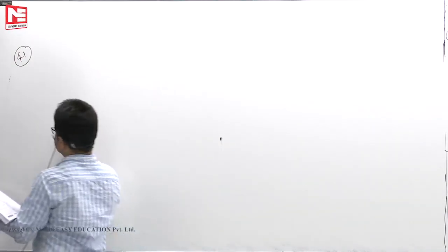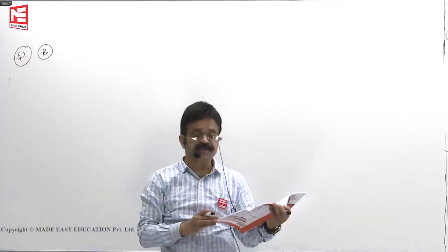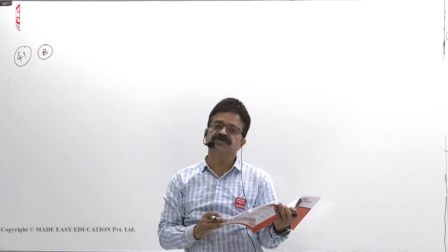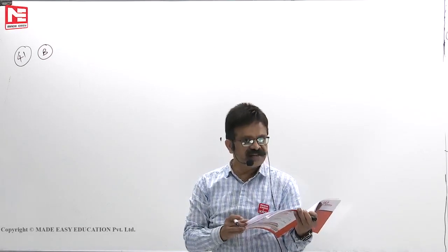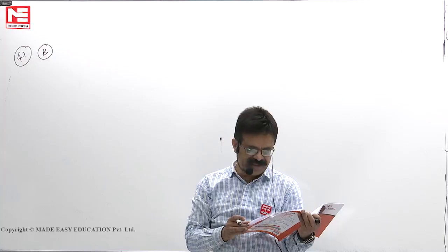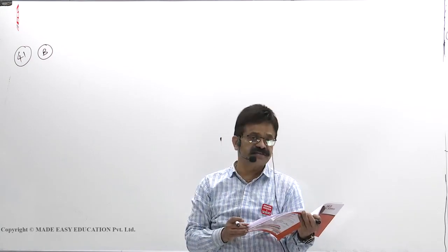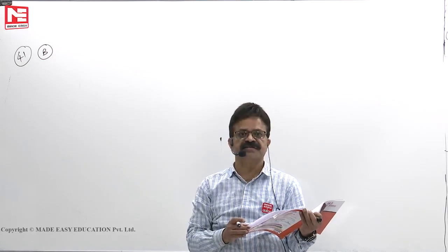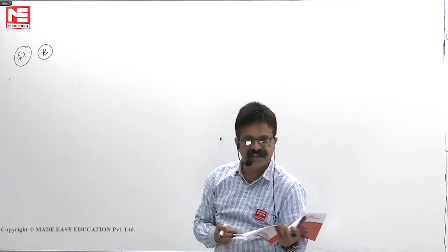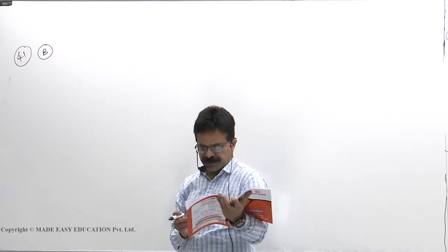41b. Once he says may not be caused, it is only valid for determinate structures. For a linear elastic determinate structure, may not be caused is fine. But if it is a linear elastic indeterminate structure, internal stresses may be caused due to lack of fit. So that statement you cannot say. Okay. Next, 42.